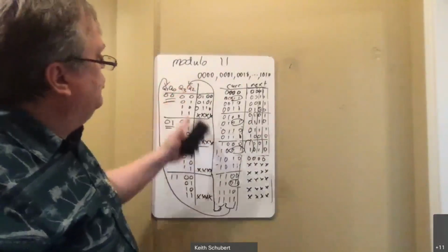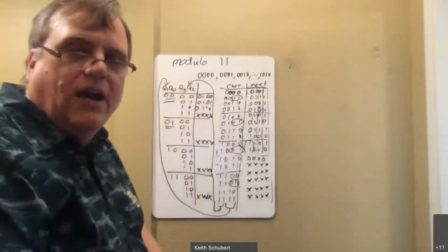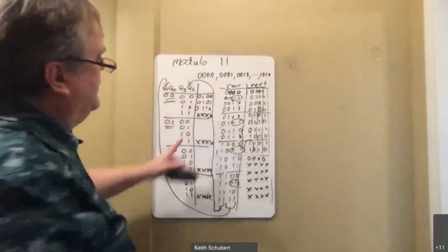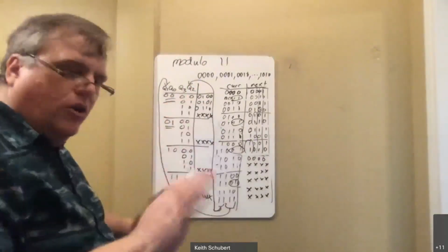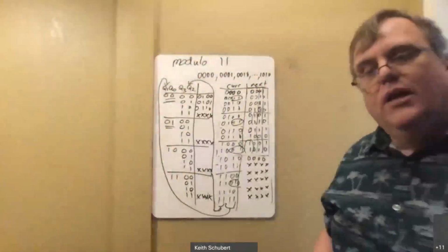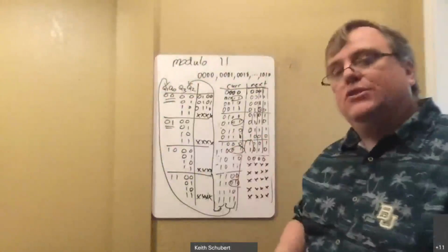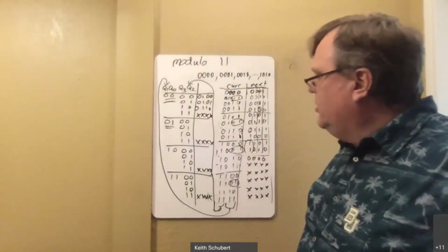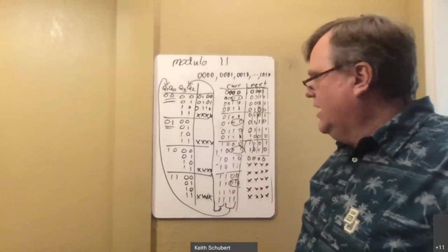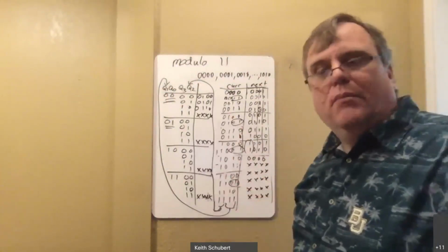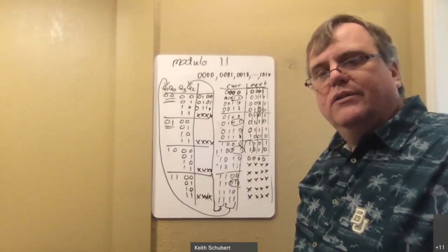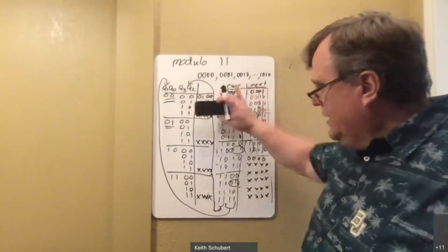And you can use either Q2 or Q3 to be patterns now. Right? And these X's will give you enough flexibility that you don't have to deal with any of the weird cases. Right? So that's a pretty big hint. So if you use this, you have a decent likelihood of being able to fill out the rest of the table and therefore fill in my mux design for me. All right. Hopefully that helps.